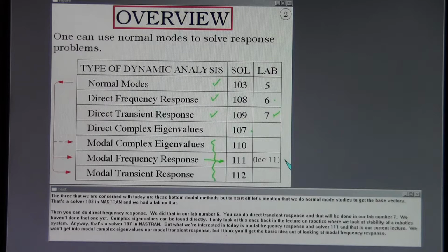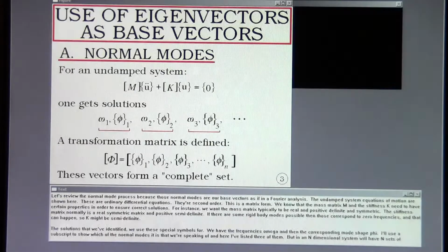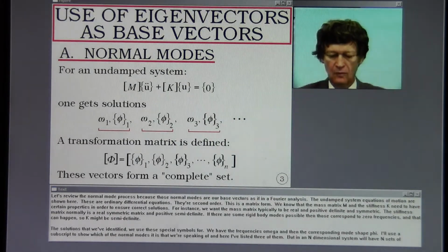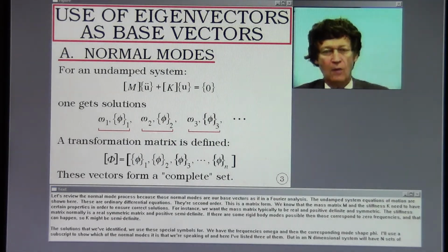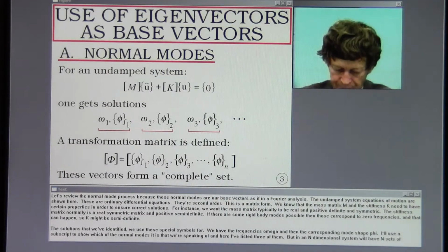We won't get into modal complex eigenvalues nor modal transient response, but I think you'll get the basic idea out of looking at modal frequency response. Let's review the normal mode process, because those normal modes are our base vectors, as if in a Fourier analysis.